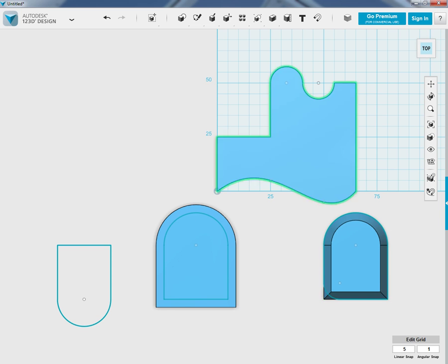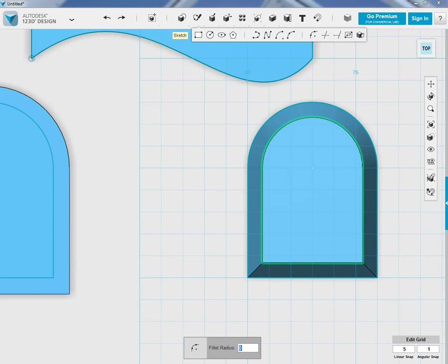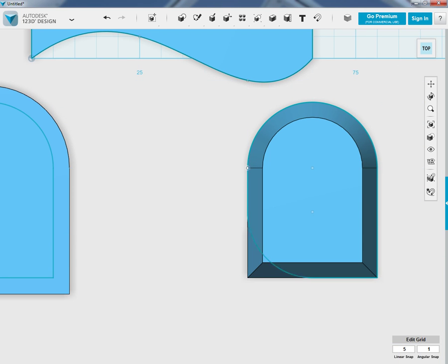No, that did not work at all. Okay, let's undo that. Let's try that one again. Fillet on this shape. Okay, thank you. I want to fillet here. I don't want to fillet here. No, I can move this arrow here, no problems. 7.5. It's very, very small, that's why. Let's make it 15. That's more like it. That's what I wanted. Okay, press enter there.